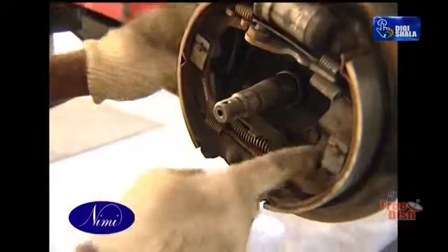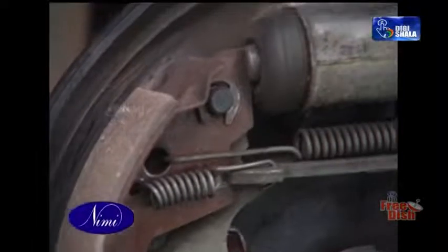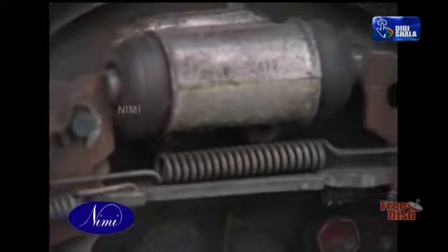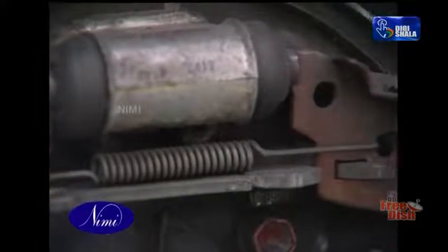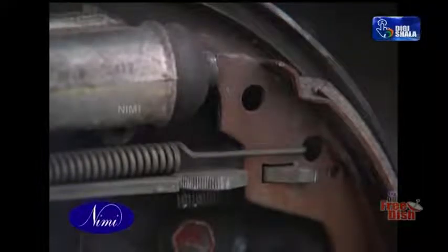The rotation of the drum gives a self-energizing action called the self-servo, which causes: 1. Leading shoe to be forced towards the drum, 2. Trailing shoe to be forced away from the drum. The leading shoe is the first shoe after the expander in the direction of rotation.